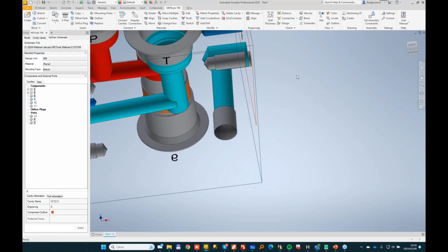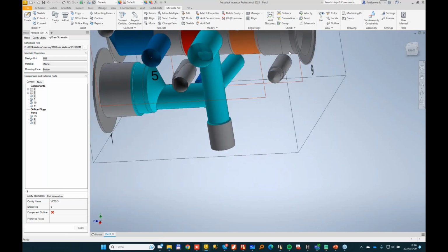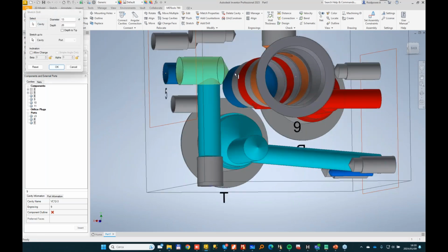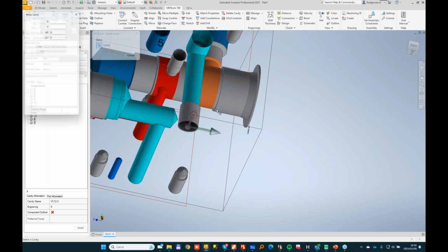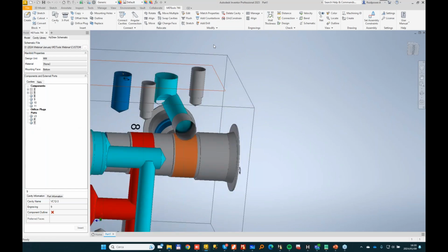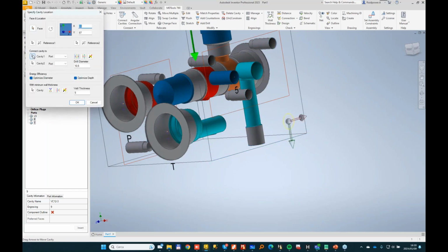It's important to pay attention because expander, well, I prefer really to use threaded plugs, but I know that for compactness in mobile hydraulics, people use a lot of expander, but really you need to pay attention to where they are positioned to prevent failure or leakage. Similarly, I copy my plug and do the other connection here.